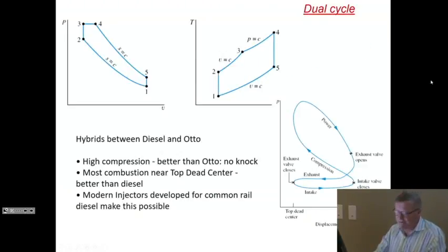which of course leads one to the concept of why don't we make a hybrid where we can use the benefit of the Otto cycle as far as RC, the cutoff ratio, goes, so we try to keep the ignition as short as possible at top dead center, but yet we do an ignition where we inject fuel at top dead center. We don't just compress the fuel during the whole compression stroke. And these engines do exist, hybrids between diesels and Ottos, and they are made possible because you have diesel injector technology, but yet a gasoline type cycle.